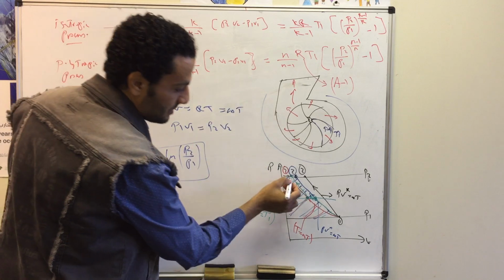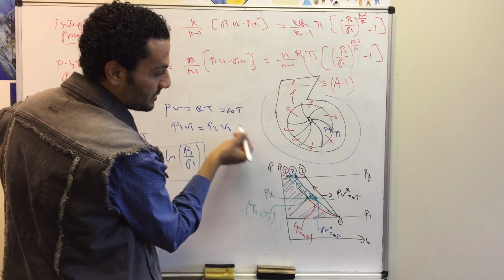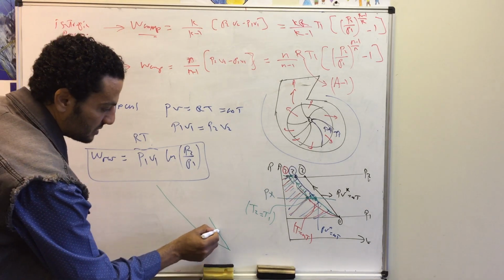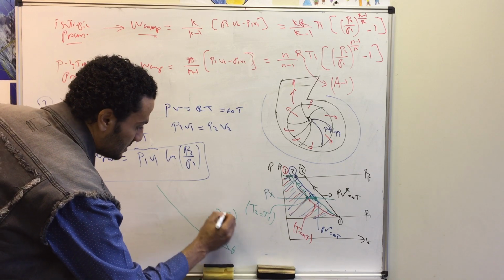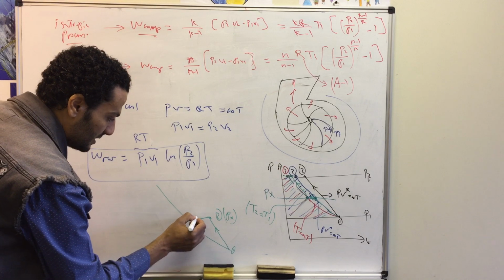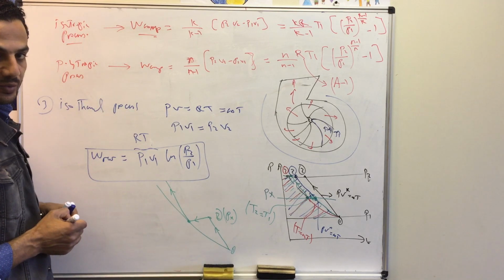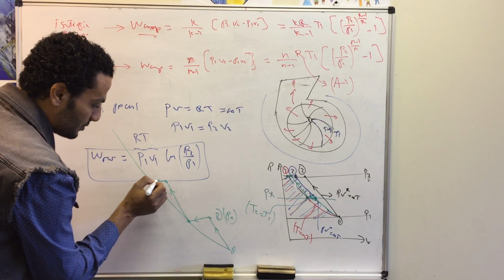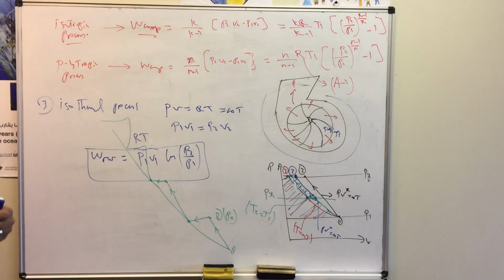Then if the pressure is a little higher, we will cool down from this point until we reach the isothermal line. Then do another polytropic process. So if this is the isothermal line, I'm doing a polytropic process from pressure P1 up to an intermediate pressure, at point 2, which is pressure Px. Then cool down until we reach the isothermal line. Then do another compression process following a polytropic process up to another pressure here. Then again do a cooling process until you reach this temperature. So we will be going very close to the isothermal line, but we cannot follow exactly the isothermal line.